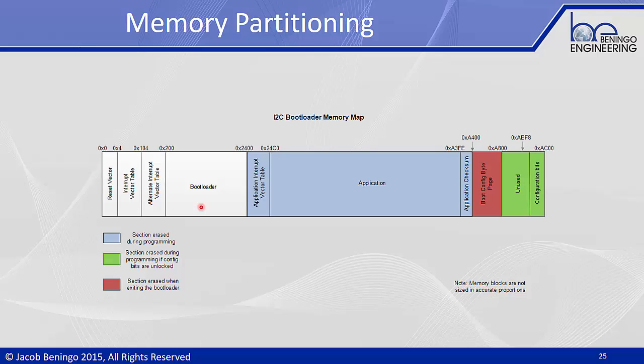Because if I put a bootloader there and I lock that area of flash space so it can't be written to, that means I can protect my bootloader so that if something goes wrong during the firmware update process and my application becomes totally corrupted, all I need to do is restart my system, and I know that my bootloader will detect that something's gone wrong, and it will boot up.